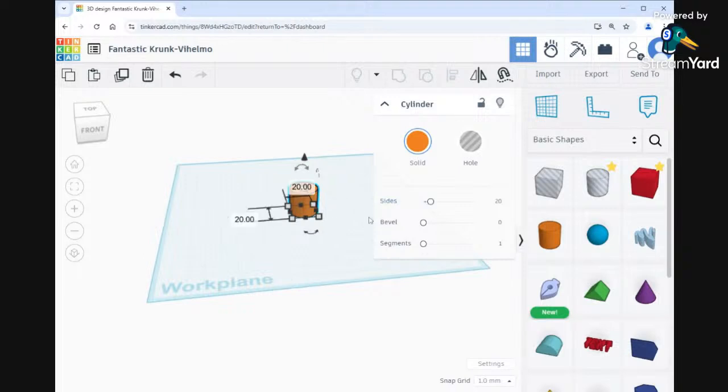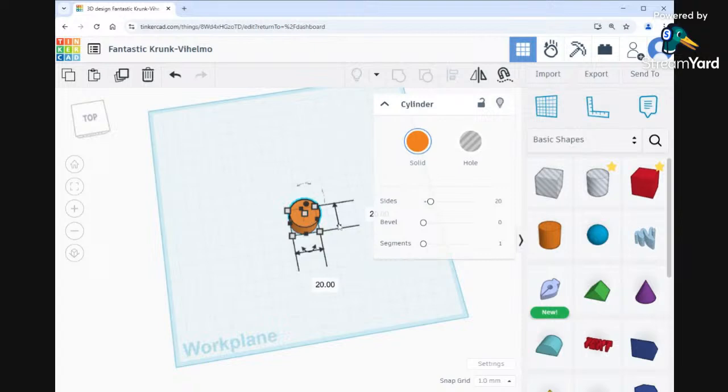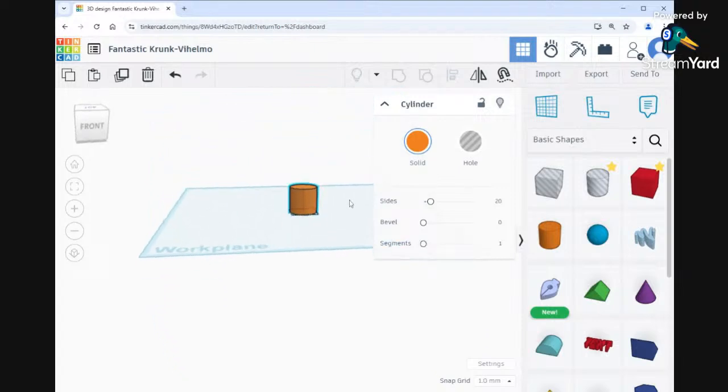So if I want to change the shape and the size of that in any way, I could do so by dragging these various points. The thing to note is that at the moment, because it's in 3 dimensions, you change its footprint, as it were, using these 4 corners. Changing its height is done using this single select button at the top. And if you want to move it up and down, you do so using this arrow up here.